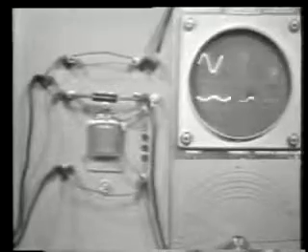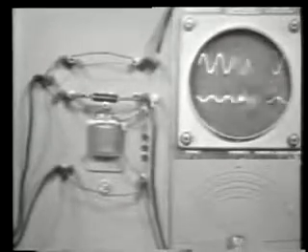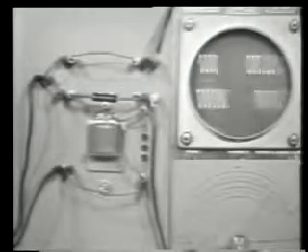Okay, let's check this out now with our demonstration. Now, as I vary the input frequency from a low of about, let's say, 200 hertz, you can see that nothing much below about 600 hertz, which is at this point, is getting through our filter. Frequencies above 600 hertz are passing through, though. We're passing the high frequencies.